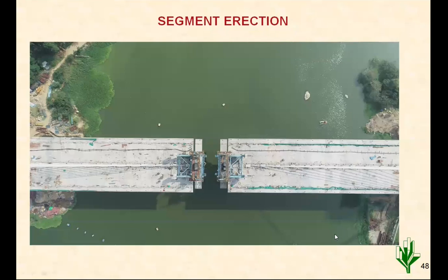So up to now we have seen three case studies. One is the Nagpur cable-stayed bridge, then the second is the Bardhaman cable-stayed bridge. Both were almost similar except for the material chosen for the construction. That is, the first one was totally RCC deck, whereas the second one was a steel composite girder. The third one is the extradosed bridge, and that is prestressed segmental also. So those are all segments, and internal prestress is also there. With the internal prestress and external cables, this kind of extradosed bridge is done.